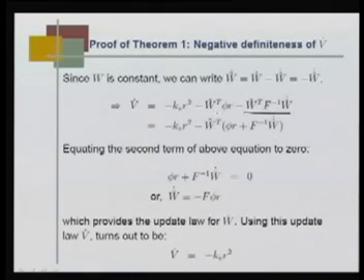So, I can club these two terms as W tilde transpose times phi r plus F inverse W hat dot. What we need is that the system will be stable if the derivative of the Lyapunov function is negative definite. For that, if I can make this term 0, then V dot can be minus k v r square.